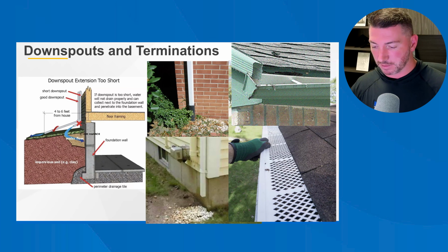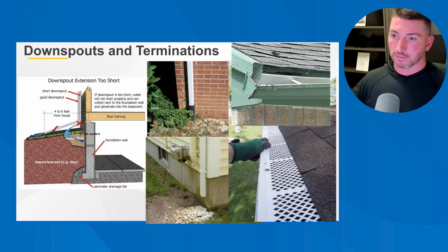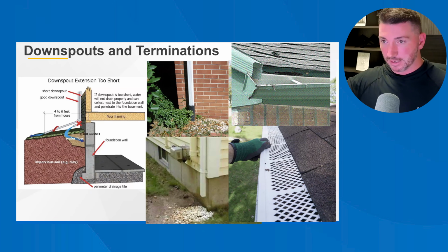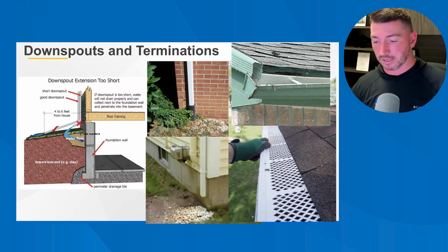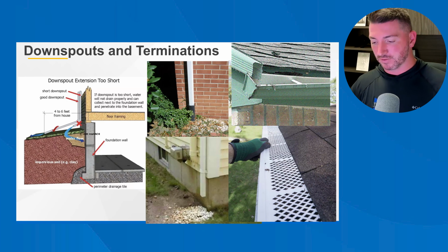Most downspouts are made of the same material as the gutter system, so they tend to suffer from similar problems, with a few twists, especially in the area of mechanical damage from proximity to high traffic areas. And one of those areas a lot of times is trash barrels, the big trash bins that everybody puts their trash in outside. The lid is flipped open and bangs the downspout, and you're reducing the capacity of that downspout whenever you crush it.